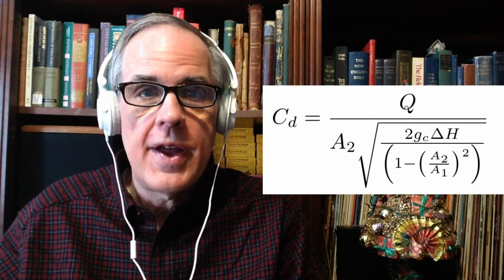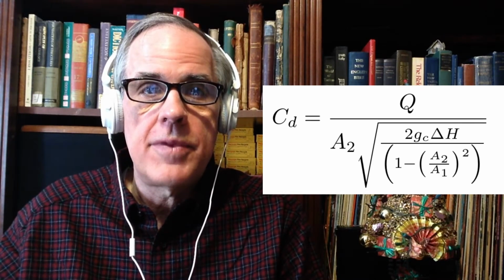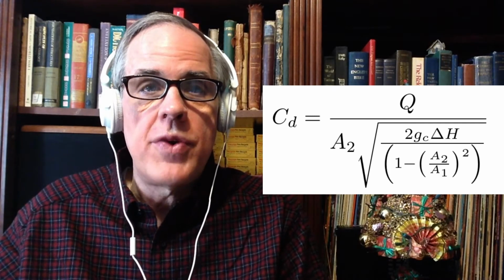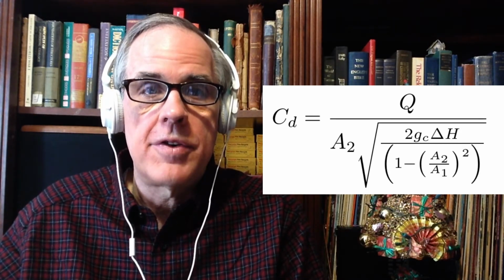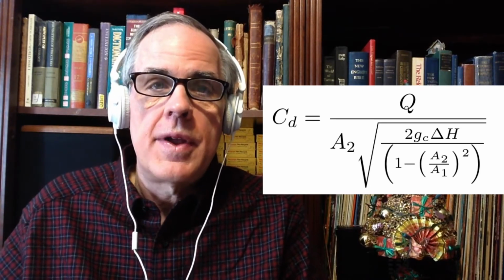If we know the coefficient of discharge for a certain device, and we know the geometry of it, and we know the head difference that the manometer is measuring, we can end up being able to estimate the flow. Conversely, if we know the flow, then we can solve for the coefficient of discharge and calibrate the flow device. Traditionally, that's how it's been done. So at this point, we have an equation where we can use the physical characteristics of a flow measuring device to estimate the flow. For years, that's the way it was done. It's still a useful exercise because it shows us how we can use these devices in this way, and at the same time take into consideration whatever viscous losses are in the device.